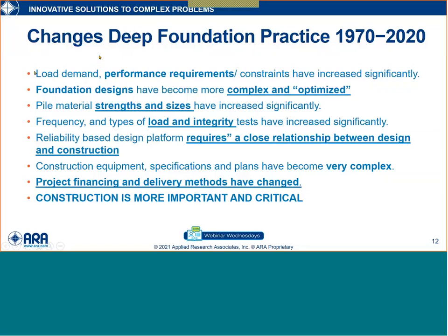And if we focus on a few of these, the first one, load demand, performance requirements and constraints for deep foundation geotechnical features have grown enormously. That places a huge burden on the geotechnical designer and the construction. Pile materials, and I use the term pile generically, have increased in strength, availability, and sizes. We think of drilled foundations. The largest drilled shaft I've ever worked on was 15 foot in diameter. The deepest shaft I've worked on was in excess of 300 feet. Those dwarf by orders of magnitude what one was accustomed to in state of practice some time ago.